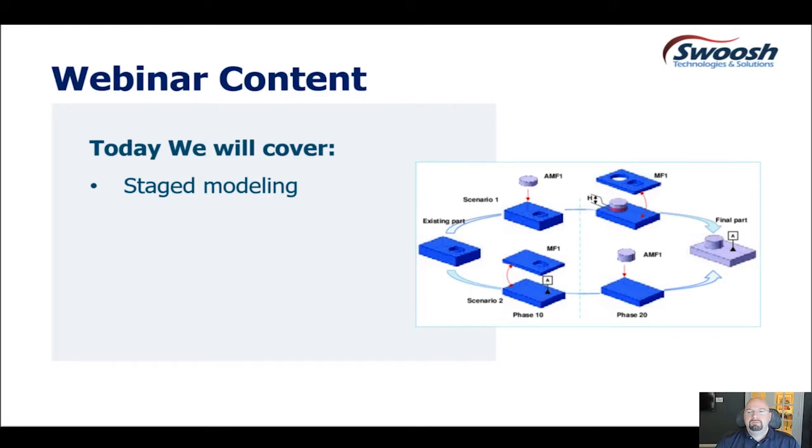The benefits here: using stage modeling inside of NX is going to allow the user to streamline their manufacturing processes by using existing CAD models at the various design stages and reuse the information from the model to quickly create parts that will represent the design at the various stages of manufacturing. Stage modeling also allows for the quick reuse of the embedded model-based definition and PMI to add it to the other manufacturing stages or the different part files that are generated at each stage of manufacturing here.